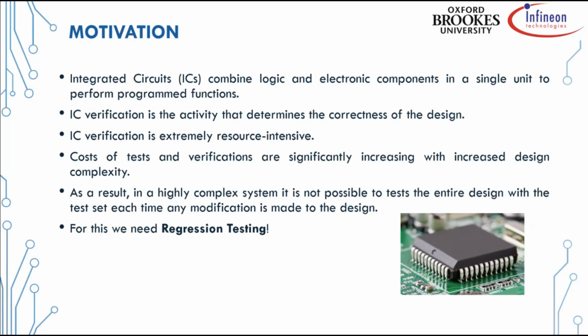Regression testing basically focuses on checking the changes made to a particular part of the IC design, and the check is to see if the change you introduced has not impacted any existing functionalities or the blocks in a particular IC.